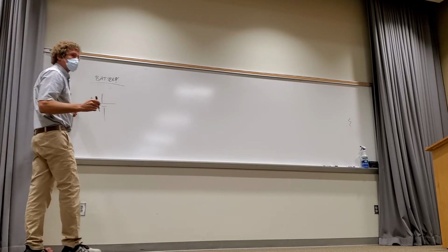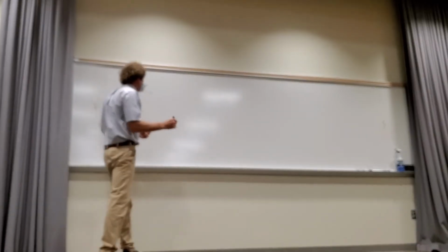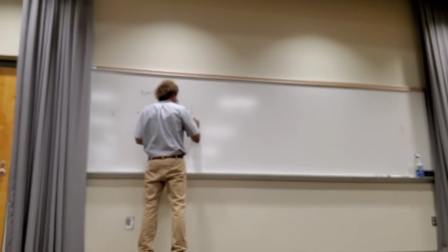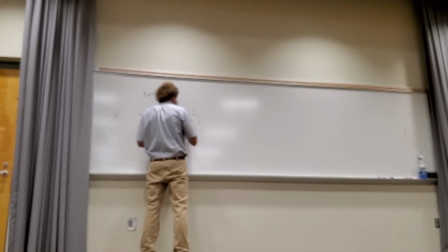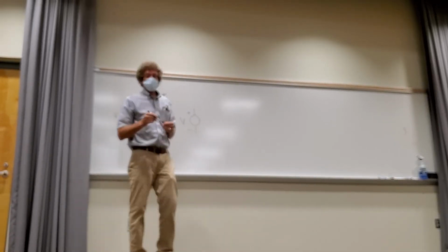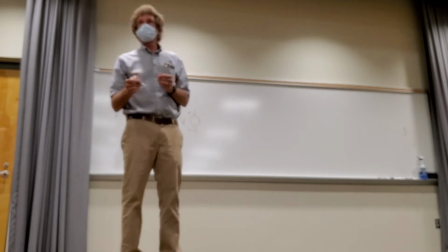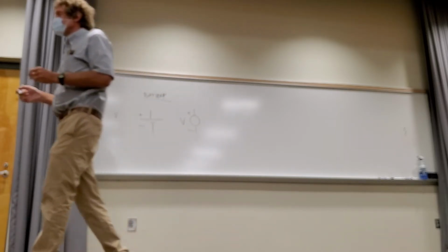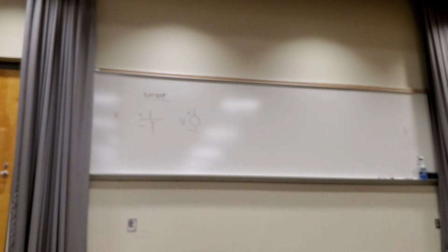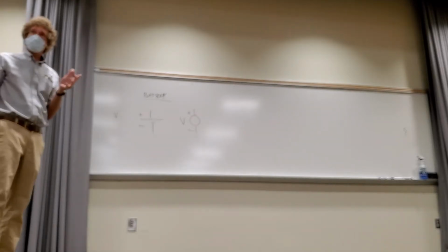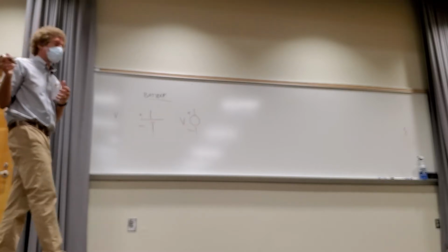So this is the voltage source. Another symbol for a voltage source can be this. If that says V equals 12 volts, it's assumed DC, and DC stands for direct current. It means nothing changes with time. You all know batteries are not time-varying output voltages, right? The way you get a time-varying phenomena is change the load or change the resistance it's hooked up to, and then you will get a different value of current, and we're going to get to that.